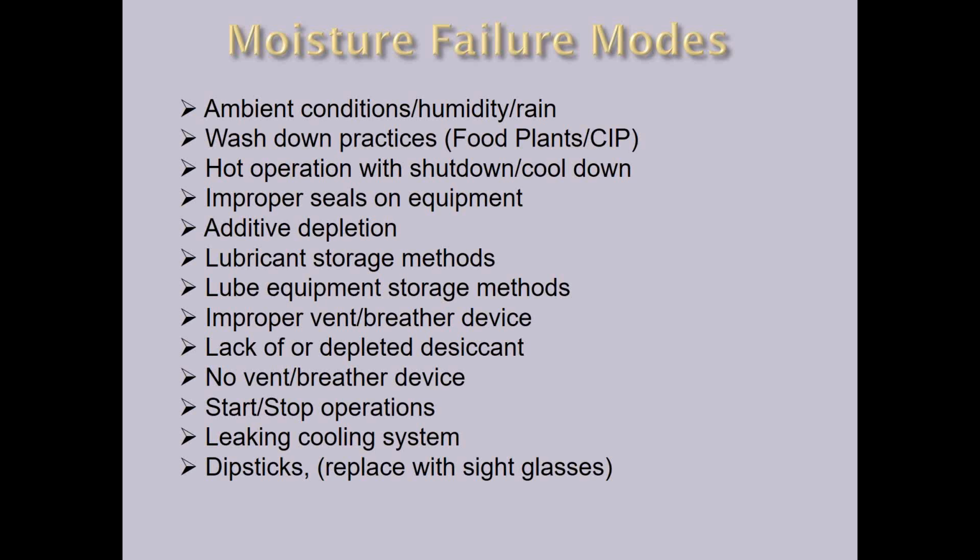Start-stop operations where moisture comes in. The component heats up, we shut it off, cools down. I think we got that up here at the top. You know, a leaky cooling system. I found this at a number of plants. They have cooling coils in there, and either the cooling is too cool, where it's getting below the ambient temp, we're causing condensation, or the cooling system may be leaking.